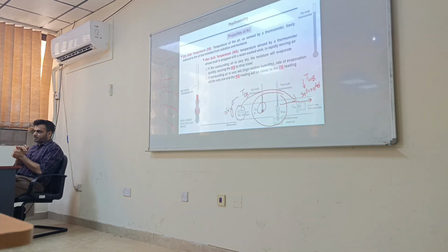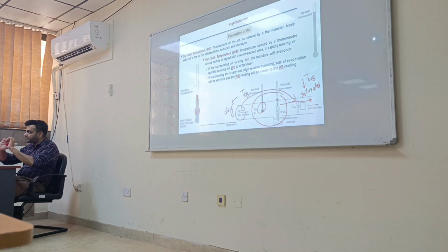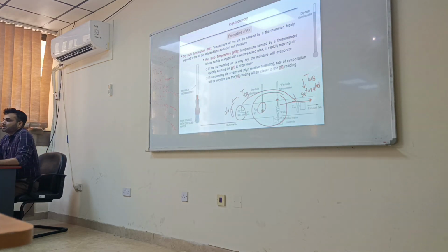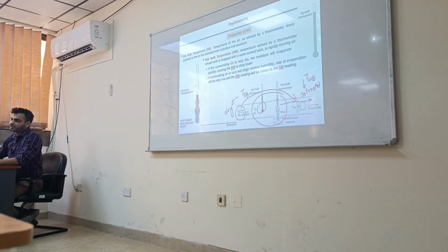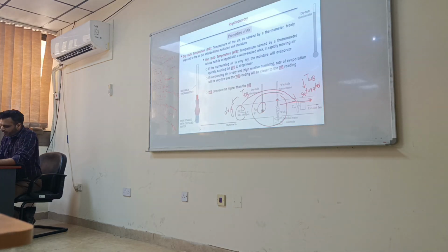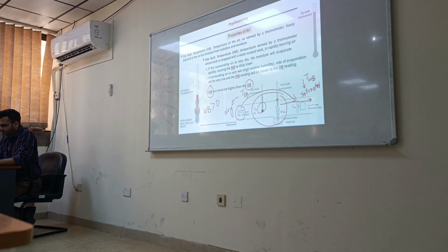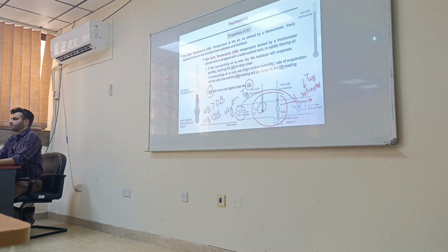Okay. So wet bulb simply means, you will wait until this temperature does not drop anymore. It means now maximum evaporation has occurred. Now air cannot hold more water vapor. So that's why when it is very humid outside, even our sweat doesn't evaporate, right? When it is already very humid. Okay, so it means wet bulb temperature can never be higher than dry bulb temperature. That is not possible. Wet bulb temperature will always be less than dry bulb temperature.